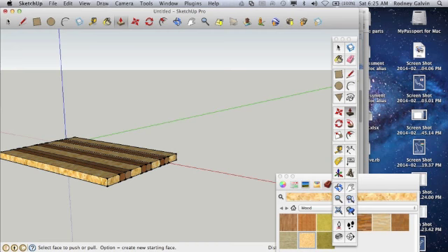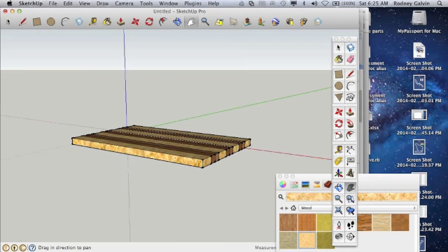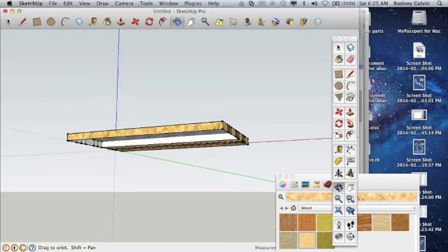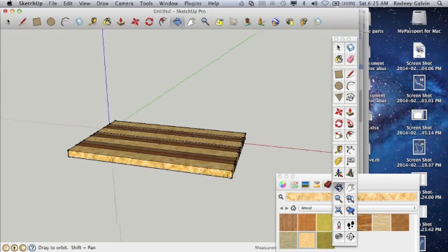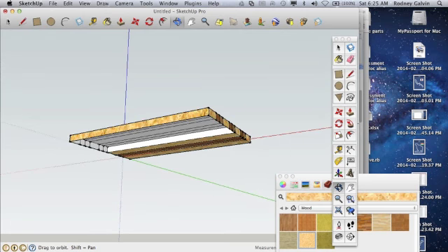I'm going to select a slightly different tool, this hand tool. I can click and drag and I can move this around. Another tool that can come in useful is this tool here, and this is called an orbit tool. So I can click on it and I can move so I can see different parts of my object. You may see that at the bottom it hasn't quite worked out, so it's filled in. So what I can do is just enter a line and I can go and draw those lines in.